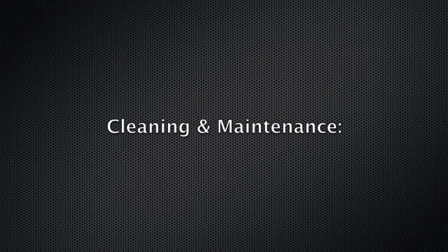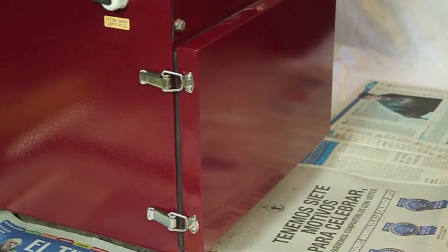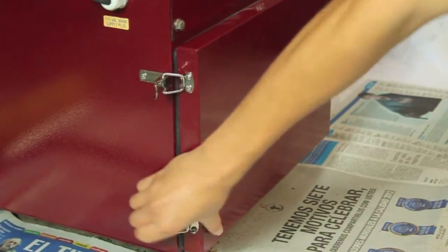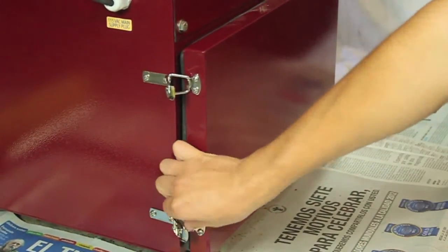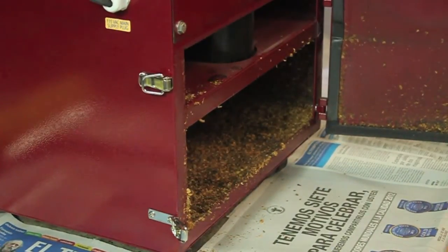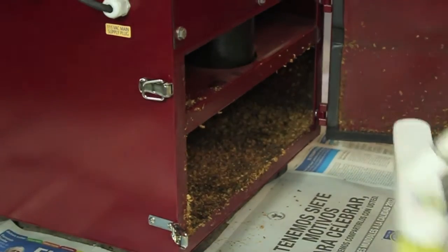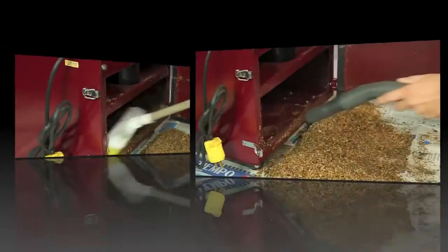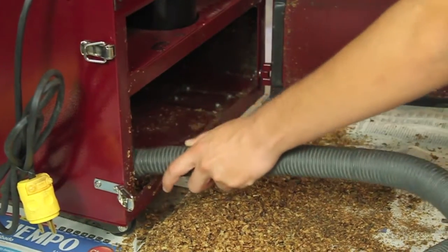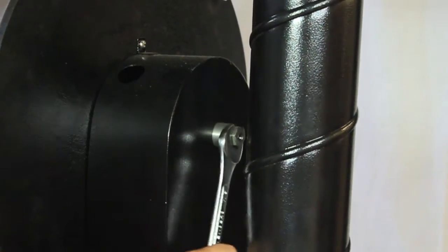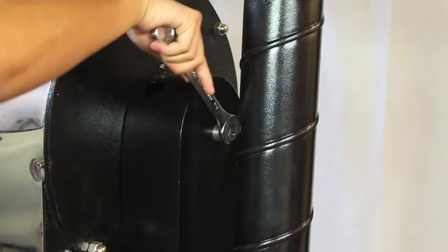Cleaning and maintenance of the machine. Open the gate located on the back of the machine. The suction duct located on the rear side of the cylinder base accumulates residues by the passing of fume and cuticles. It's necessary to avoid the residues from accumulating by cleaning this compartment constantly with a brush and using a vacuum. When energy runs out, move manually the engine to avoid damage.